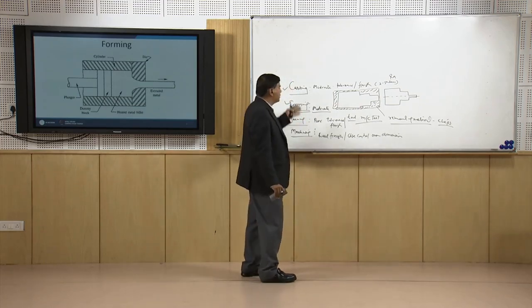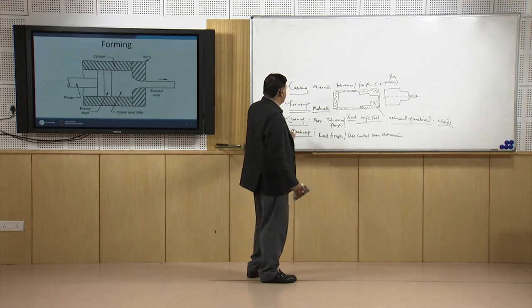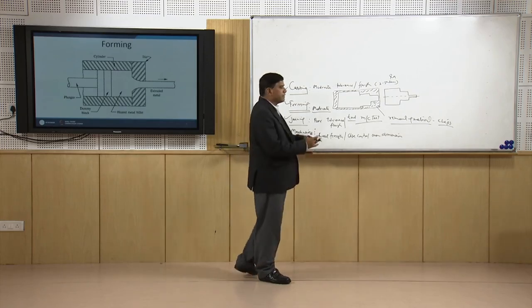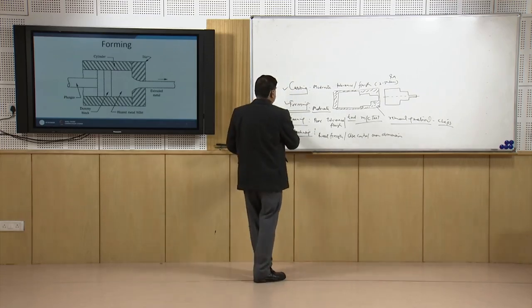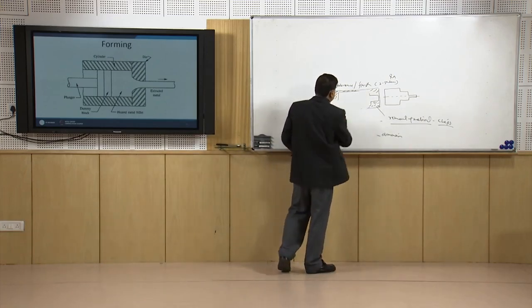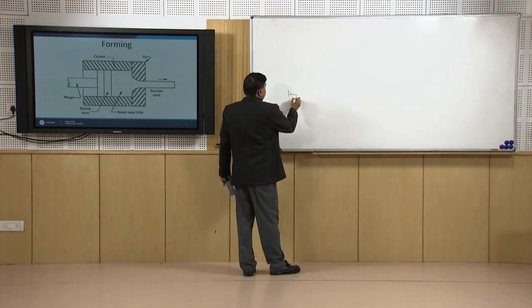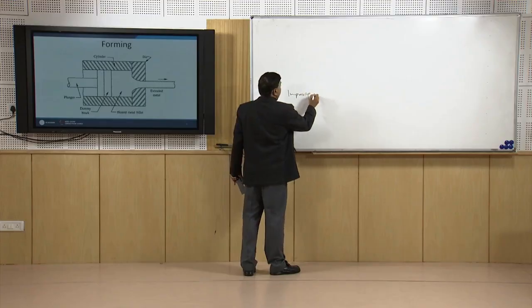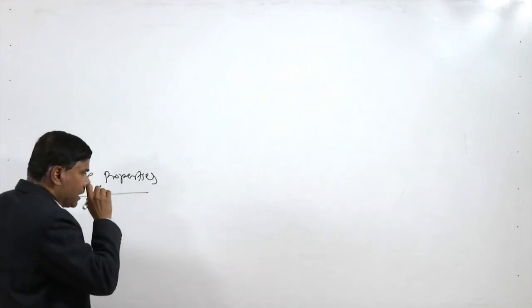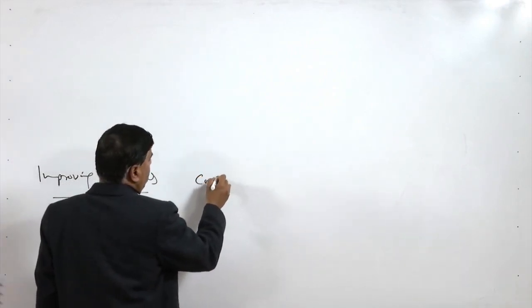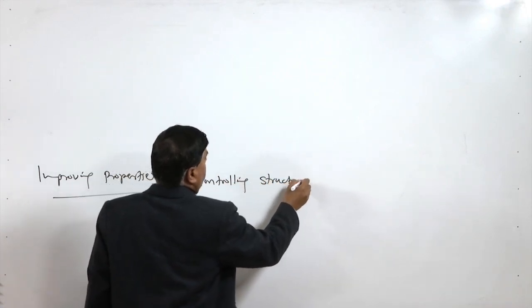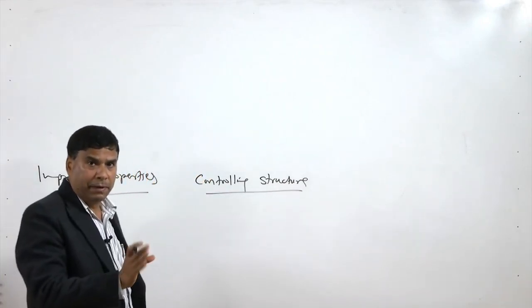This is the general approach which is used in case of the four major manufacturing processes. Likewise, there are other processes, heat treatment, case hardening, etc., and the semi finishing and finishing processes. Improving the properties and the surface properties, both these actually work on controlling the structure or microstructure of the material, so that the desired combination of properties is achieved.